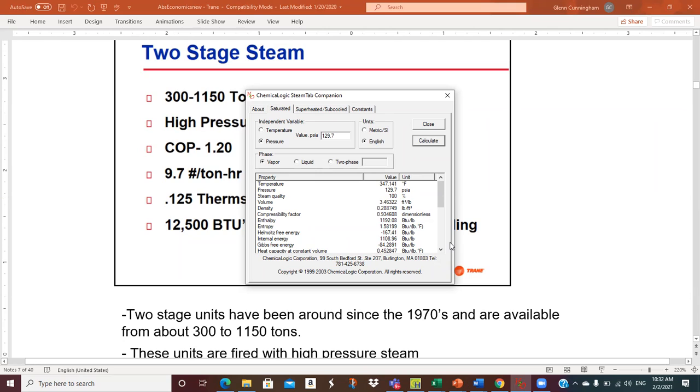Okay, so at 115 psig, when we condense a pound of steam, we get about 874 BTUs. So that's what's happening as you go up in pressure: that saturation dome gets skinnier, and so when you go up to really higher and higher pressures, you may only get 600-700 BTUs per pound of steam when you condense, okay? Because there's a lot more energy in the liquid, in the condensate, because it's so hot.